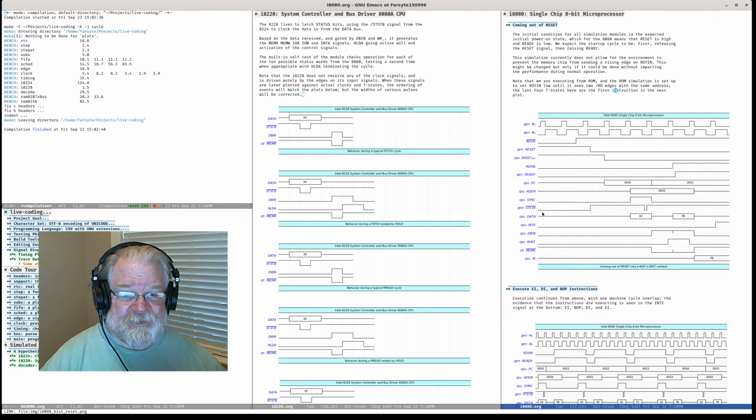Oh, also notice that the status strobe is being driven by the clock generator chip. And when we come out of reset here, when the clock generator synchronizes reset, it also releases status strobe. So we issue a sync pulse, and we've got A2 on our address bus. We are emitting the proper status. We are emitting the PC here, so the address bus has the program counter, which will go and do its fetch. Meanwhile, behind the scenes in the T2 cycle, probably here, we're incrementing PC.